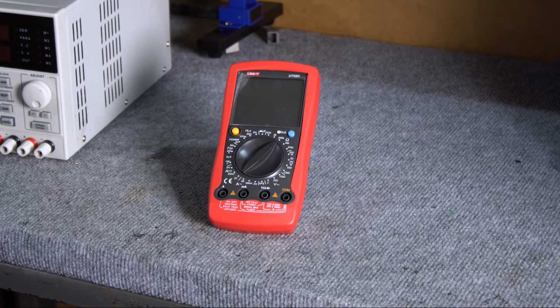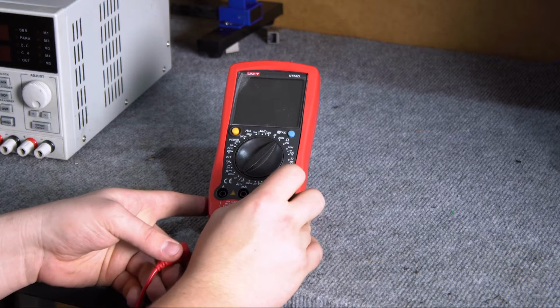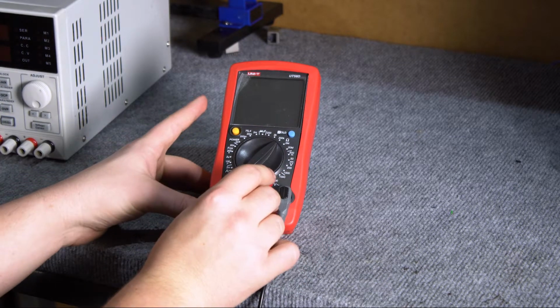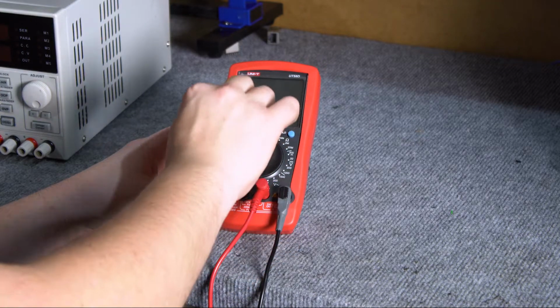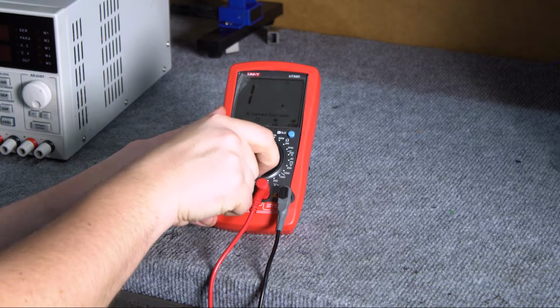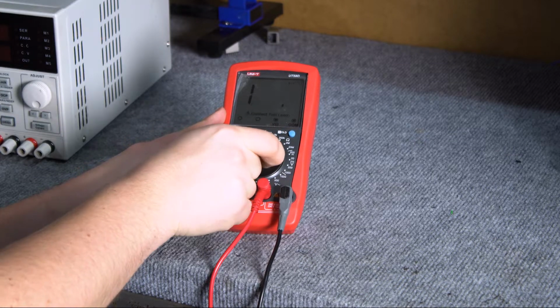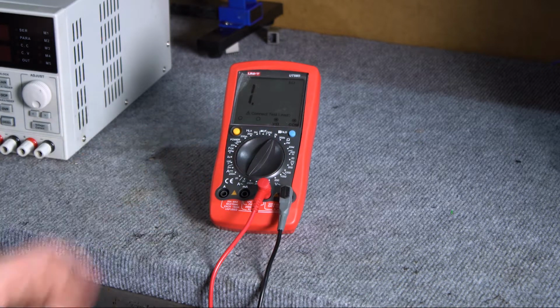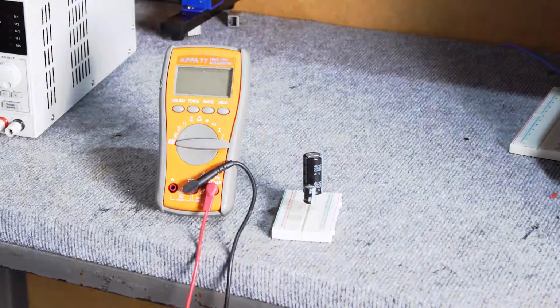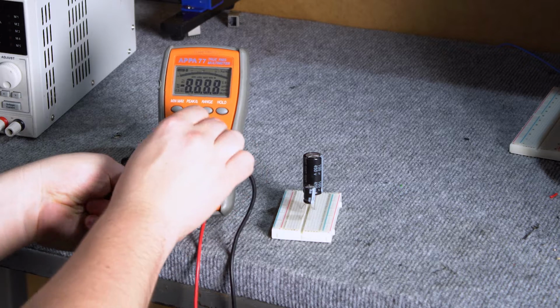The ohm meter or resistance meter is connected in parallel to the elements whose resistance is to be checked. It should be remembered that for proper checking, these elements should be desoldered. Mounted in a system, they are connected with others and the measurement result can be falsified, with the resultant resistance seen from between the probes. We measure capacitors with the capacitance meter.